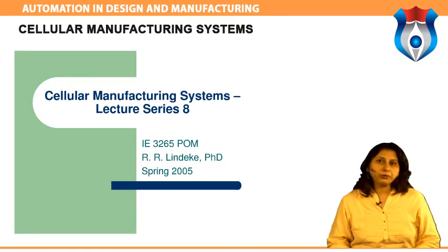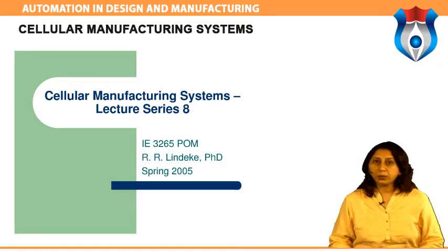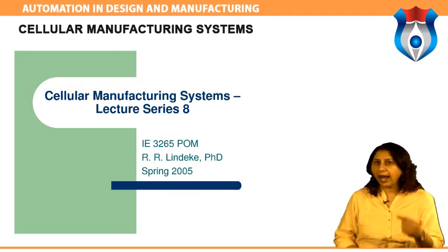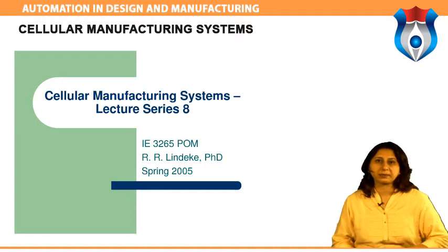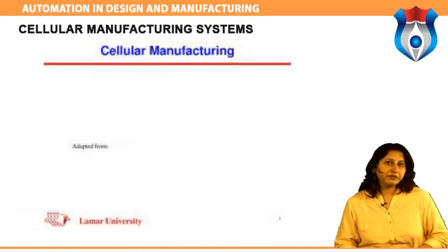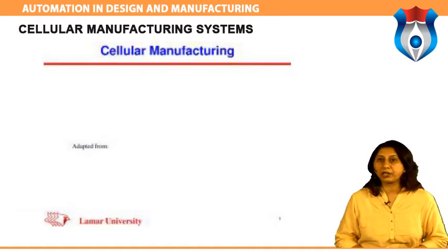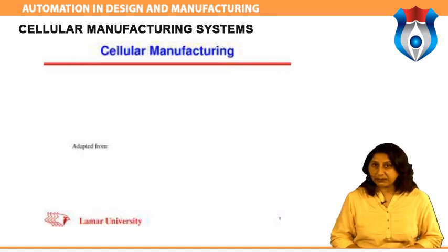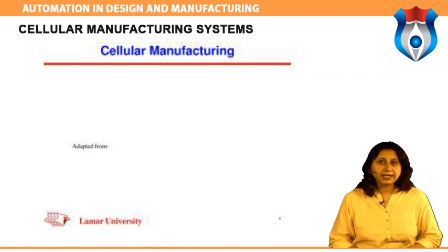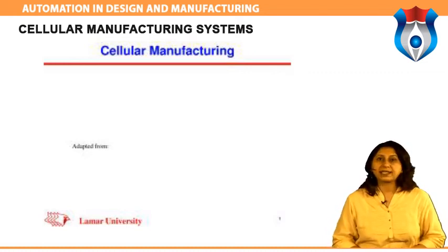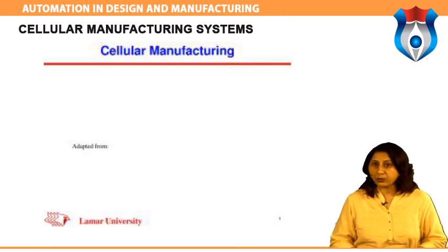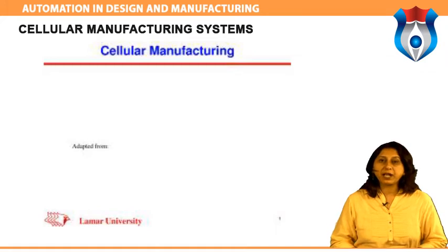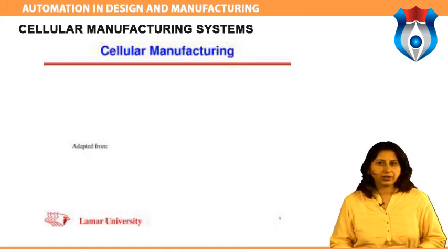Given enough volume of products to work with, work cells have been proven by experience to be faster and more efficient in manufacturing than batch and queue systems. Because of the free flow of materials in cellular manufacturing, it has the ability to produce products just in time. As such, no inventories that have already undergone processing at one station will be left unprocessed in another station.